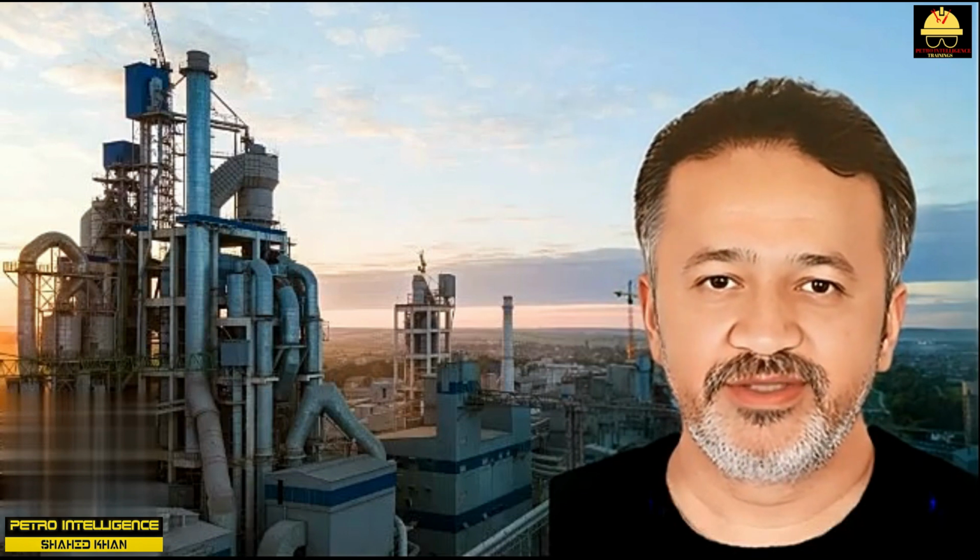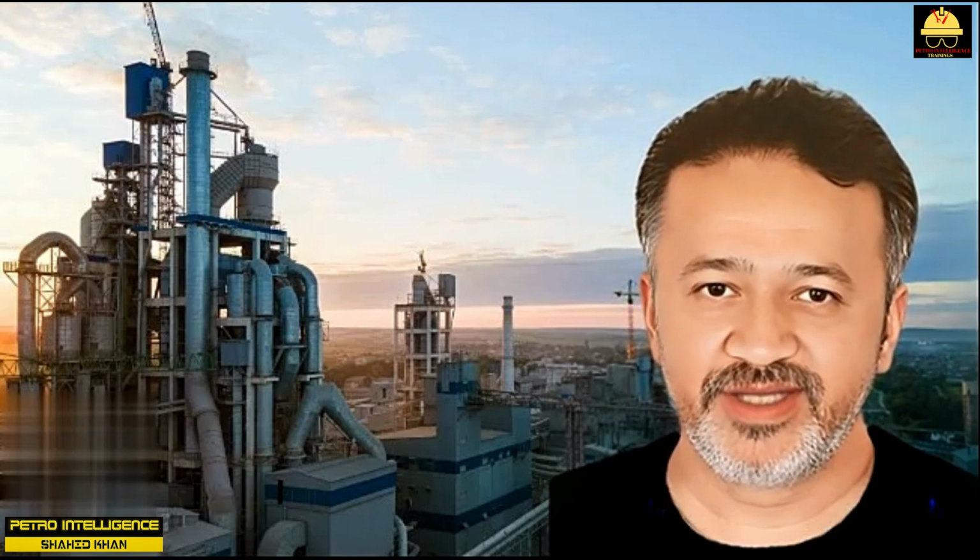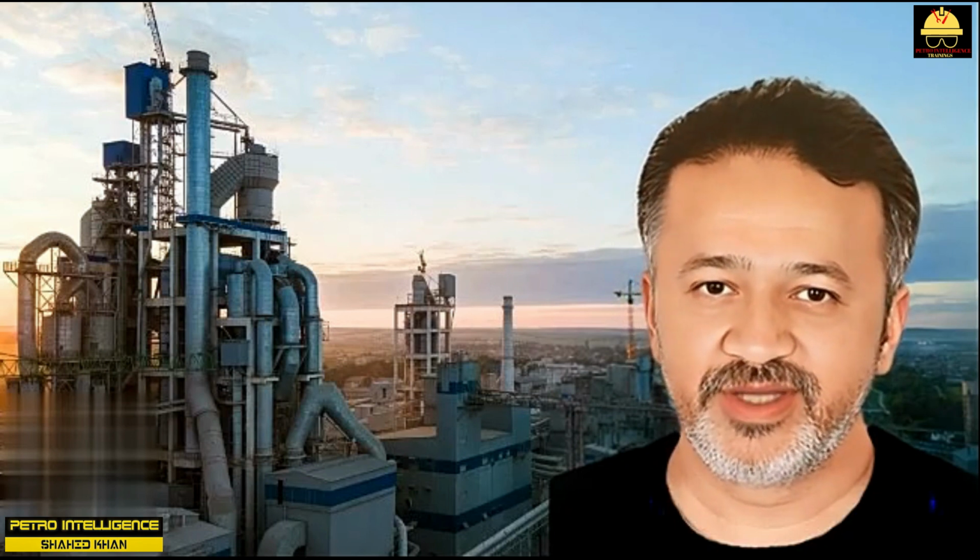Erosive tube side liquid velocities. Tube side fouling and plugging is greatly reduced by high velocity. For clean cooling water, a velocity of over 3 feet per second is good. For heavy crude oil contaminated with sediments and salts, a minimum velocity is about 6 feet per second. For cracking unit slurry oil contaminated with catalyst fines, a velocity of less than 5 feet per second will promote tube plugging with catalyst. The delta P varies with velocity squared.